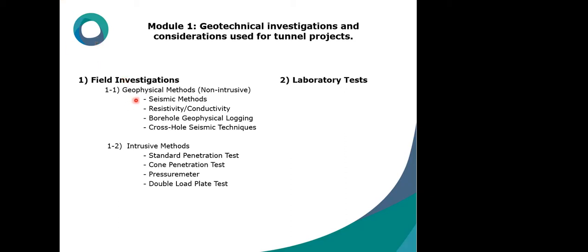So here we have geophysical methods, non-intrusive and intrusive methods, and we divided them into 4 categories: seismic method, resistivity, conductivity, borehole geophysical logging, cross-hole seismic techniques, and intrusive methods divided into standard penetration test, cone penetration test, pressure meter, and double load plate test.